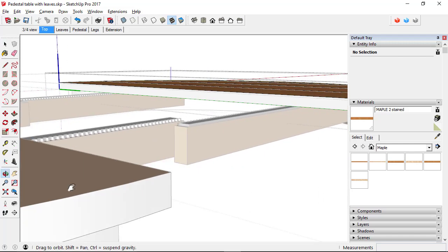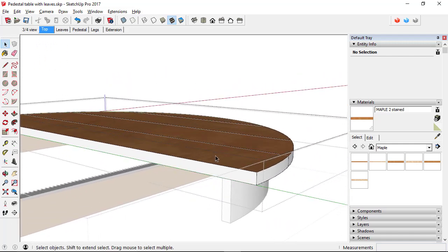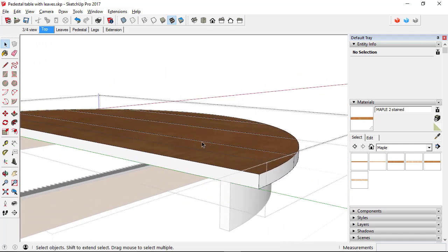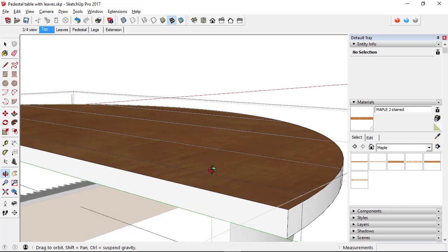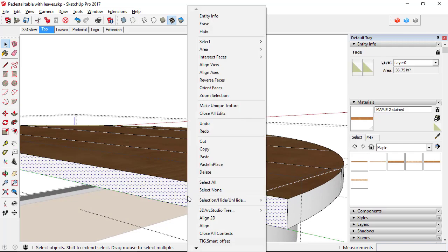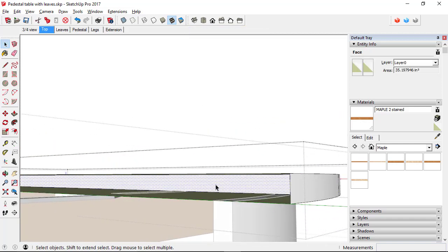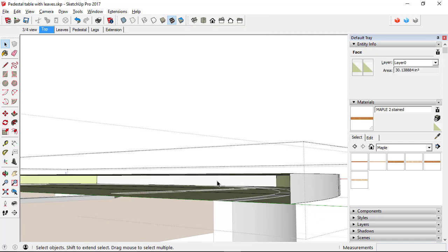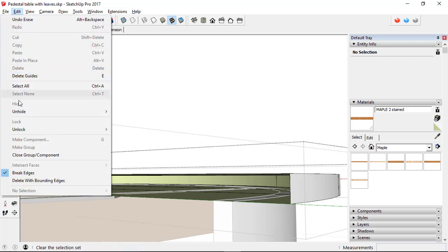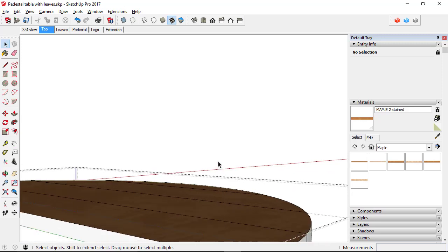And then there's internal faces, which is why we get these white edges or white lines along the black. It's the face showing through because the graphics card can't deal with that properly. So I'm going to hide this edge face for a moment and then select those faces and delete them, and then use Edit, Unhide Last to put that back.